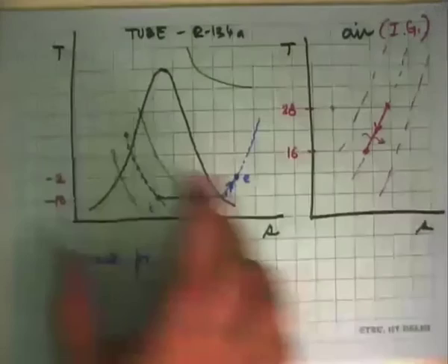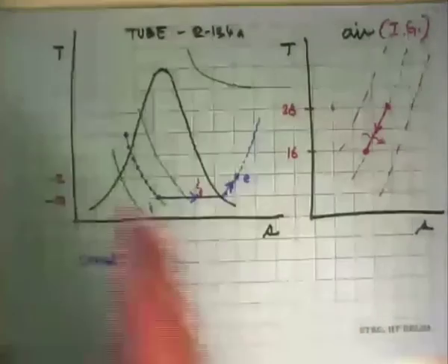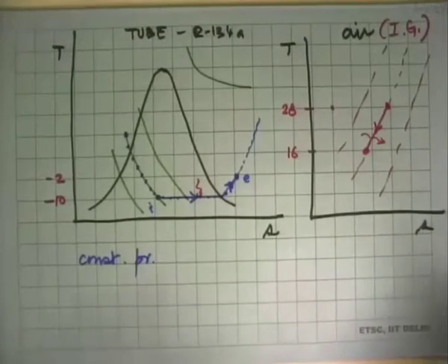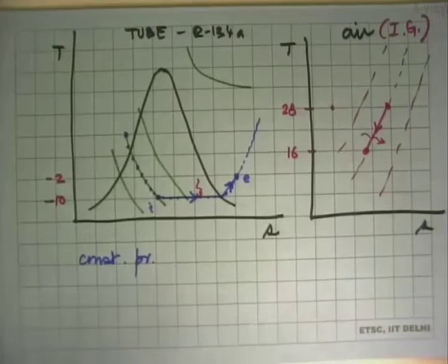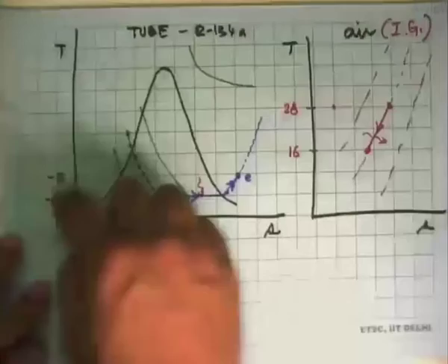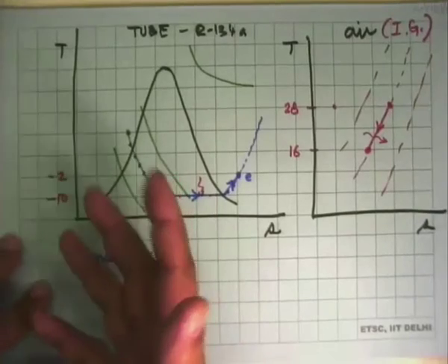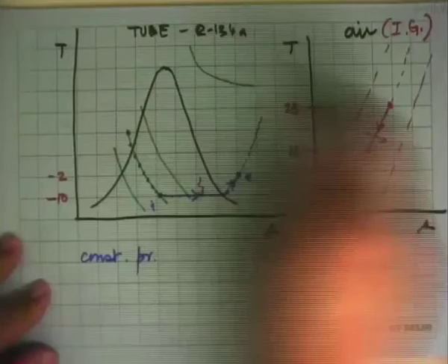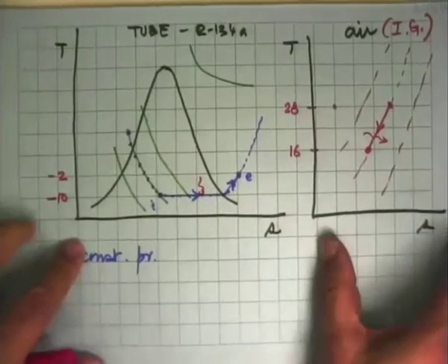Now I made two separate TS diagrams to clearly illustrate what was happening in both cases. And say, well, can I join these two diagrams to make one picture? The answer is yes, it is possible. The only issue is that temperature in both cases is the same scale. It's an absolute scale of temperature. So 0 for this is the same as the 0 for this. The trouble is on the entropy side.